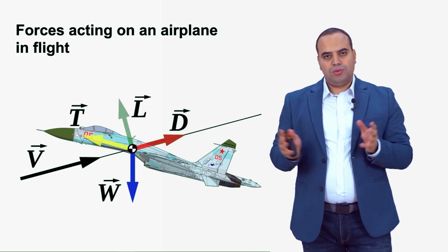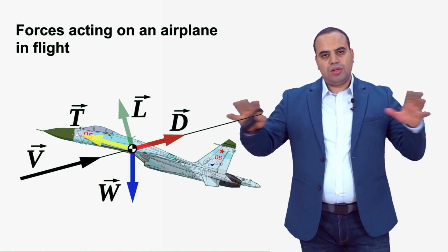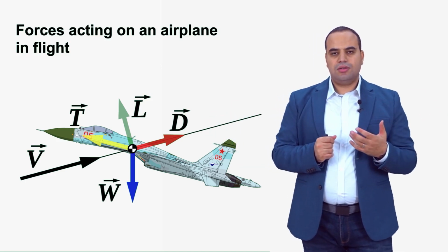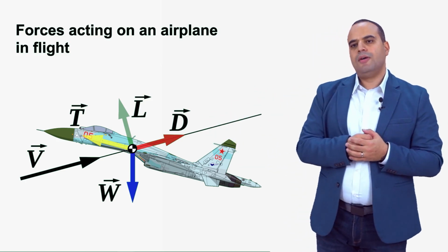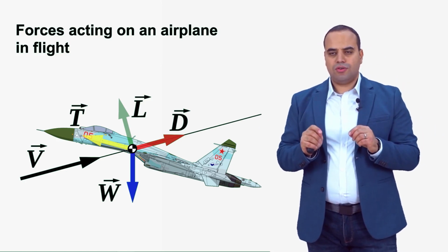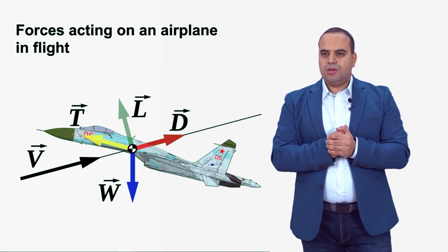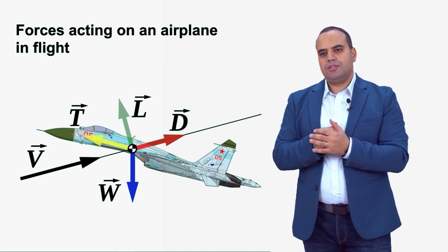These are the total forces, because, for example, the lift, the drag, the thrust, and the weight of the aircraft are distributed along the entire surface of the aircraft. It's not basically at a certain point like it is shown here. But we can, for example, assume that the mass force is applied at the center of mass, which is, for example, the W force here, the weight of the aircraft. So this is a model, if you like. This is the physical model of an aircraft in flight.